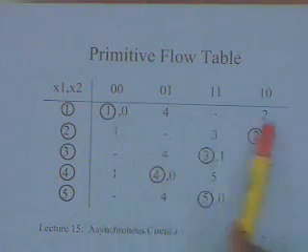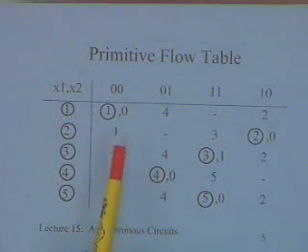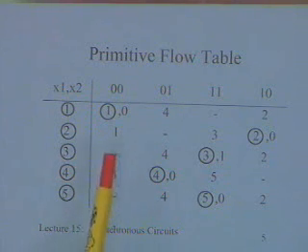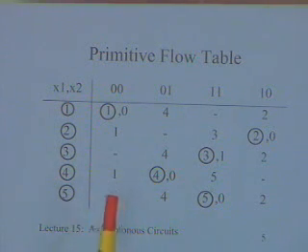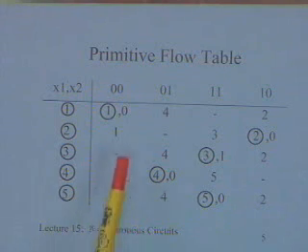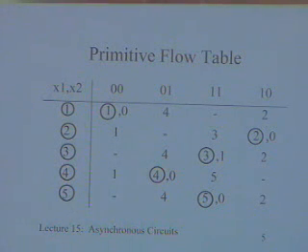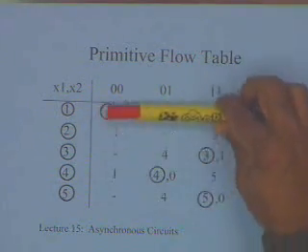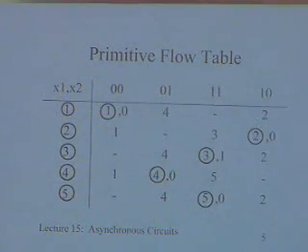So now we consider these stable states. Now what we do is we build what's called a merger graph. A merger graph is nothing but compatibility between these stable states. What is the meaning of compatibility? If I compare row-wise, if there is no difference in the states in any of the columns, then those two rows are compatible.